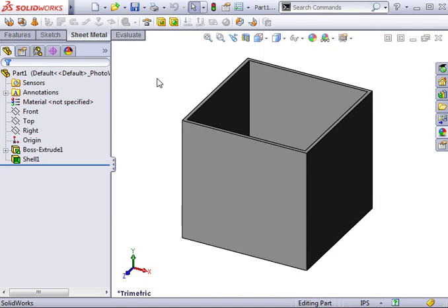or you can convert a solid part to a sheet metal part manually by using the Rip feature and later inserting bends. Let's take a look at how we can convert this simple thin-walled box into a sheet metal part using the Rip feature. The main purpose of the Rip feature is to break corners apart, so a part can be manufactured using sheet metal techniques.